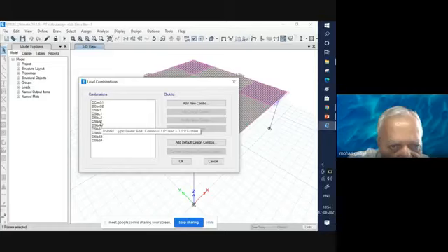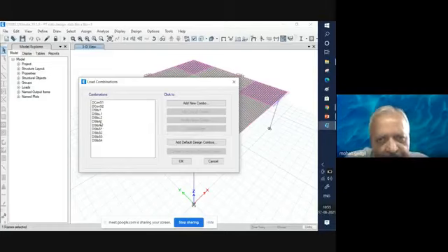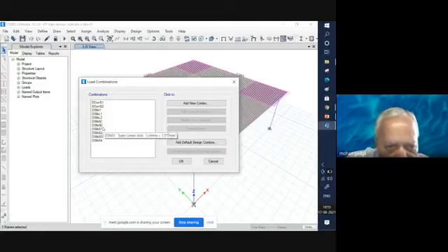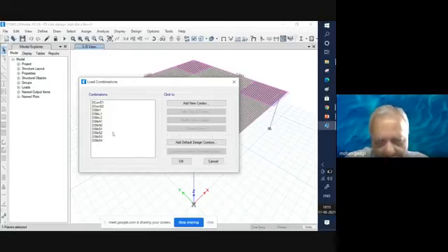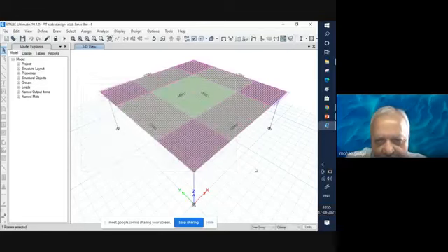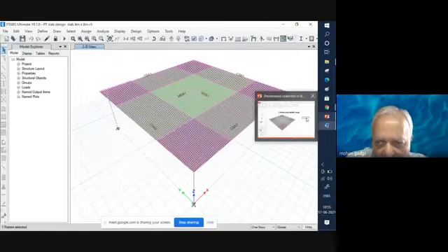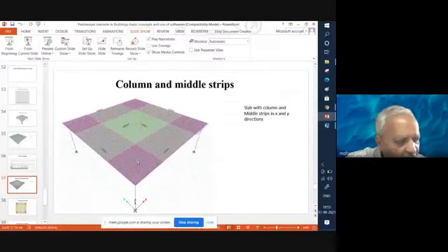So DSLB N1 considers dead load plus PT final, and N2 considers dead load plus live load plus 1 times PT final. Okay. So these are the two primary loading combinations which we have considered in our presentation, and so on. So we have this data ready.